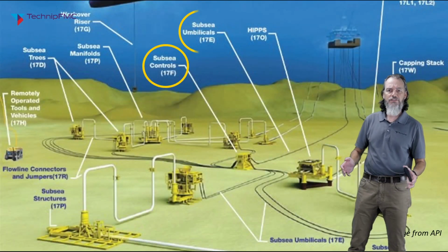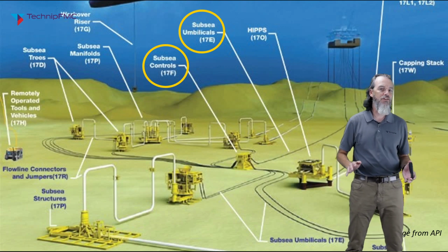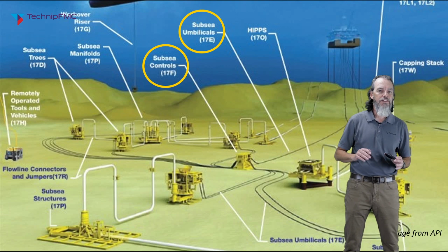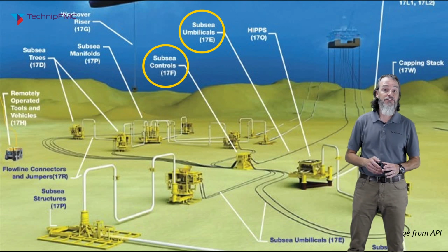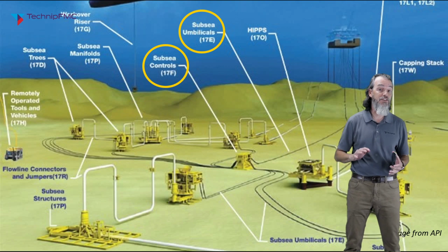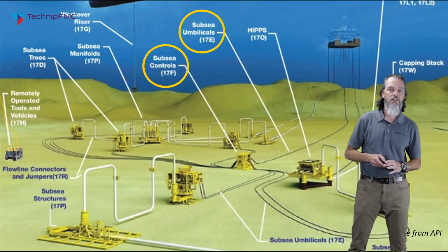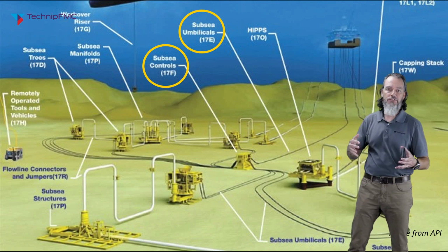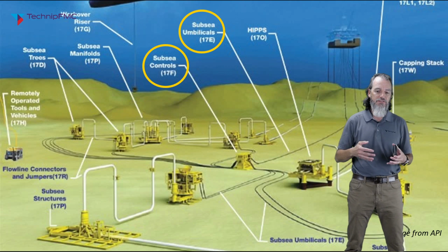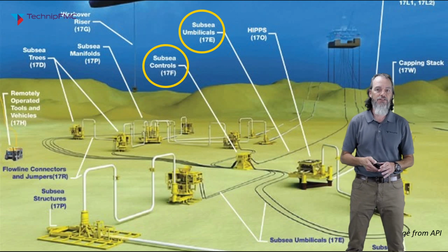In the prior talks, you saw a graphic like this showing the relevant specification for each major item in the subsea field. The example shown here illustrates the various API standards. Understanding where and how to apply the spec break between these standards is important to prevent conflicts or gaps. For instance, you see subsea umbilicals and subsea controls have a mating interface, but they use a different approach on how they define the size of tubing that they use.